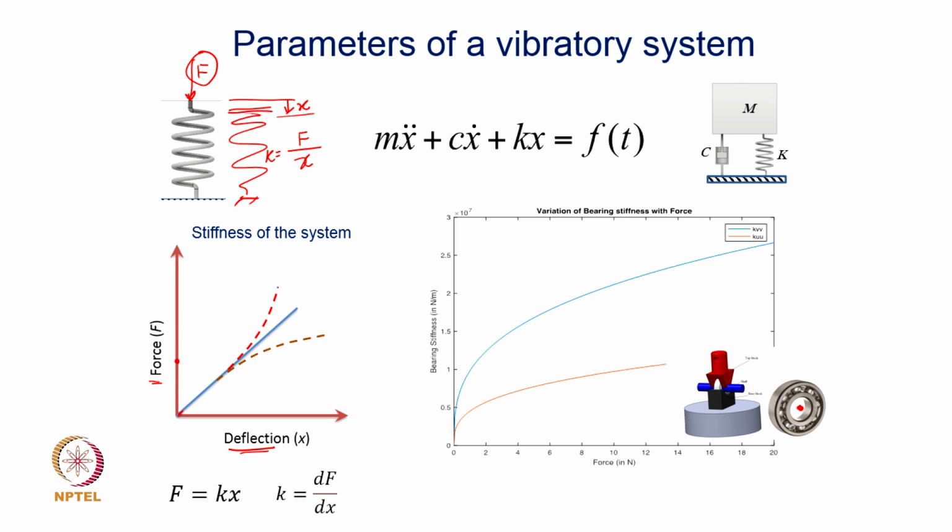Two things here. One is, most vibratory systems would have amplitudes of this vibration typically of the value or level that falls well within this range, which means that rarely do we have systems going into vibration amplitudes way beyond this limiting value, and therefore, the restoring force becoming nonlinear does not arise at all. That means, most of the times the amplitudes are well within a small amplitude range, and that is the reason why you would find a string attached to this particular equation which has been derived. This is based on the assumption that the amplitude of vibration is small, and that small actually has a lot to do with this particular range.